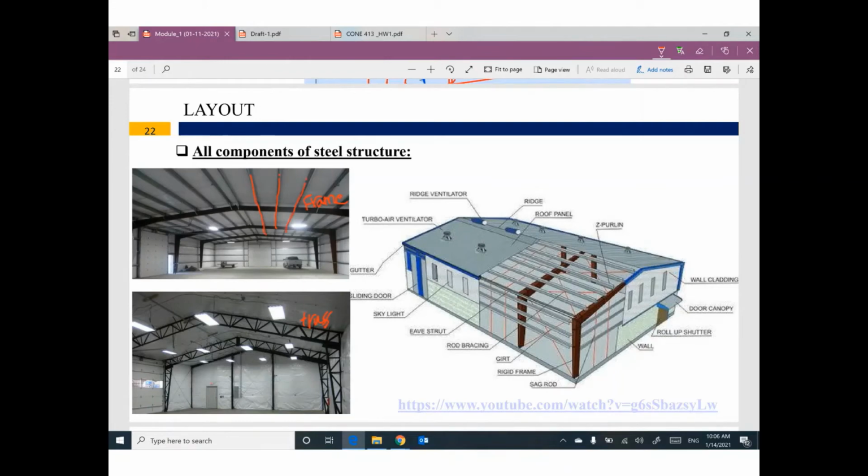These purlins are supported by the main system. For frames, we need to select this spacing between purlins. For trusses, we don't have a choice. Your purlins will be located at each joint on the truss.